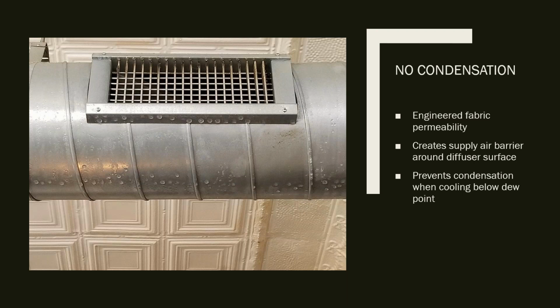But even if you do use double wall, there can still sometimes be an issue around the diffuser grills. If an owner decides to use a single wall metal duct instead in an area of high humidity, we know that single wall metal duct will sweat profusely, and the maintenance people are going to spend a lot of time cleaning that up. So you can compare fabric ducts to single wall metal ducts, with the exception that you don't have the issue of condensation in areas of high humidity.